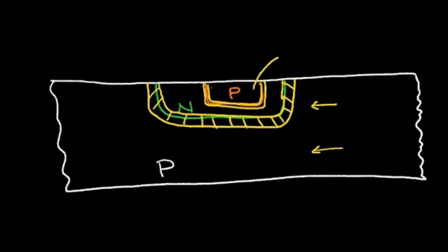And I can know that this depletion region between the P and the N material here is a thinner region, and it's thinner because the concentrations are higher. So I could just look at this structure and I know that the capacitance per unit area for this depletion region is small, and the capacitance per unit area of this depletion region is higher. So for the same amount of area, I get more capacitance in this upper junction and less capacitance in the